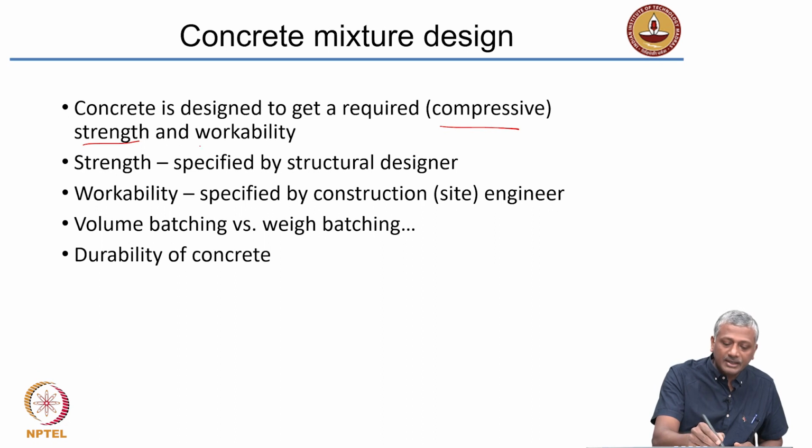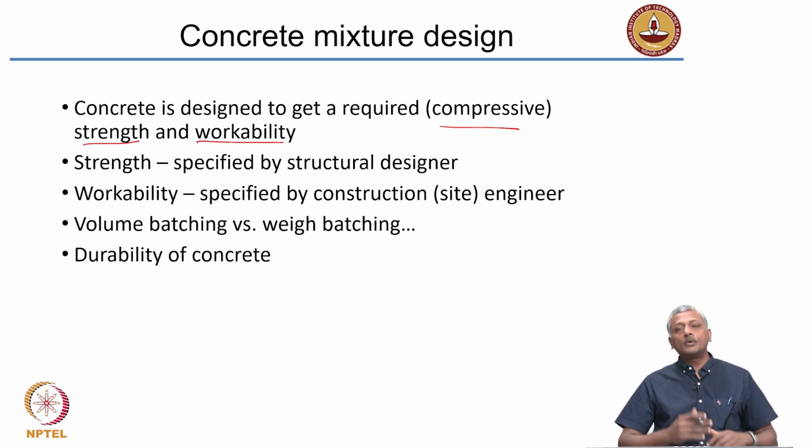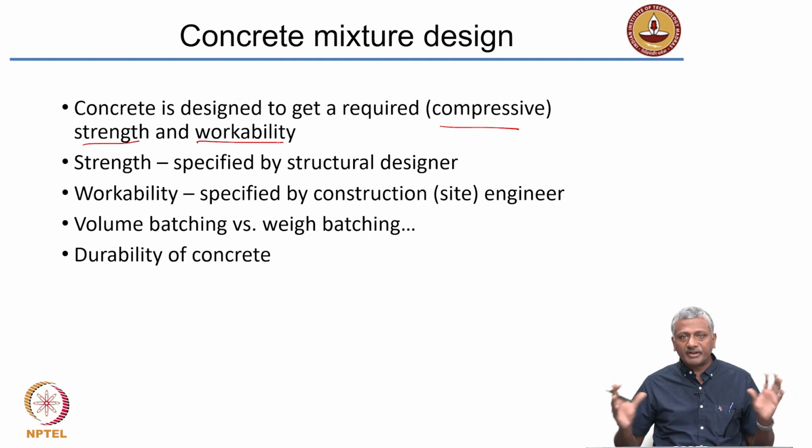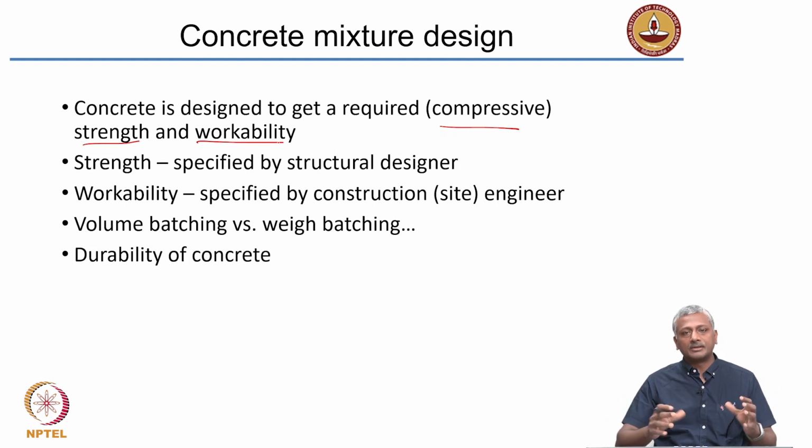Okay? And the other aspect is the workability. How easy is it for you to mix, place, compact and finish the concrete? Okay? So, workability is a term that loosely defines all these processes coming together. We will take a look at these individual processes separately. Okay? So, concrete has to be designed to achieve a certain level of workability.